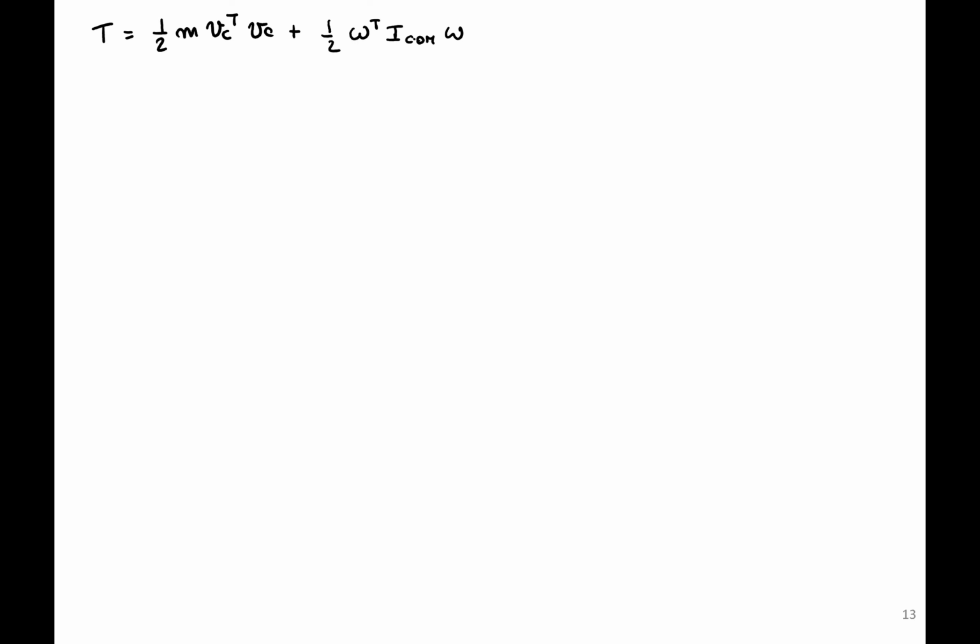The second one is the rotational contribution, because only omega appears, in a quadratic form, in the kinetic energy of the body, and it takes into account the fact that we have an inertia distribution. So we don't have a concentrated point mass, but we have a body that is extended. If we had only a point mass, we would end up only with this term.